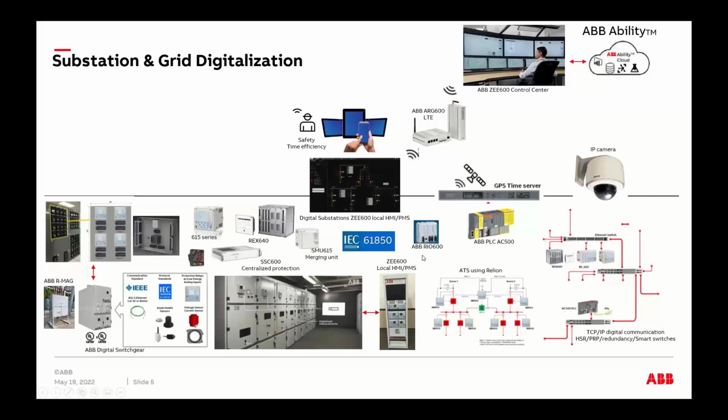At the same time, you need to think about safety of your staff. Once you're doing all this digitalization, how do I make it safe for my staff when they are exposed to the gear? Maybe the best way to do it is don't have them exposed to the gear. In our days, really, there is no need for somebody to go and pull information, for example, from a relay face-to-face at the gear, where you could do that remotely, or maybe run a wire to a control room and do it through an HMI. So there are many ways of doing this.